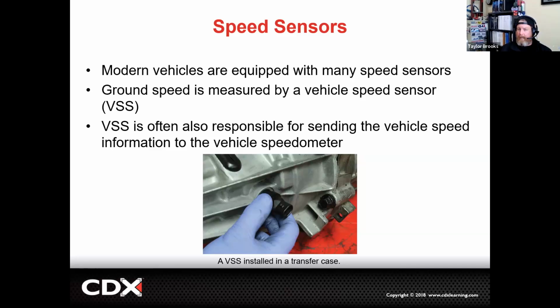It used to be when it was a mechanically driven speedometer drive, so I had to do this on my '64 Ford. You would change out the gear teeth and change out the output gear going into the speedometer drive, and you'd have to do the math based off of your tire's diameter. That way, you could accurately get the right speedometer within the realm of operation.